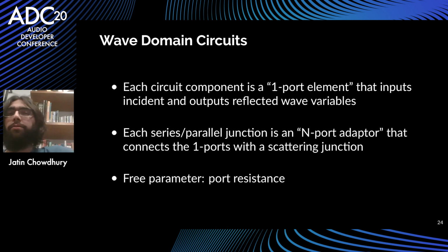So then you think of each circuit component, so your resistors and your capacitors and so on, as what's called a one-port element with an incident wave and a reflected wave. And then you connect these components with these series and parallel adapters that connect all of these wave ports with a scattering junction. And this might seem like a completely unnecessary addition of complexity that we don't really need.